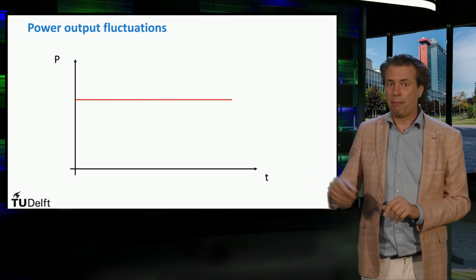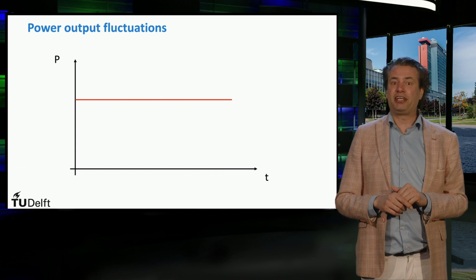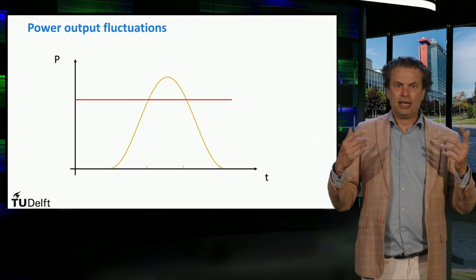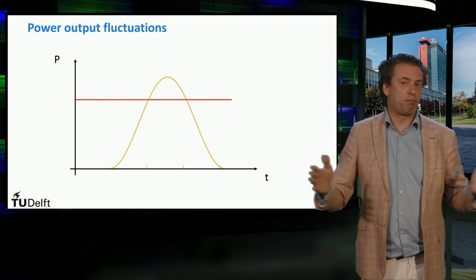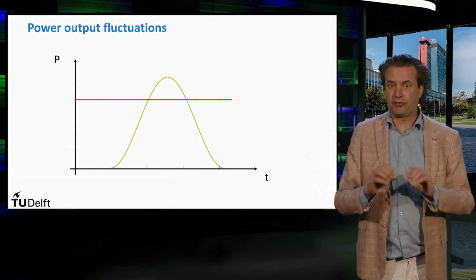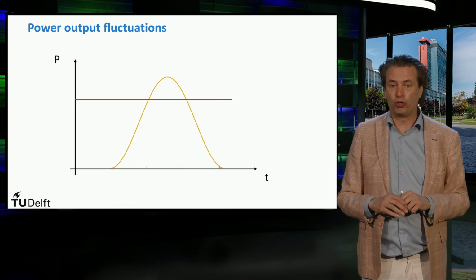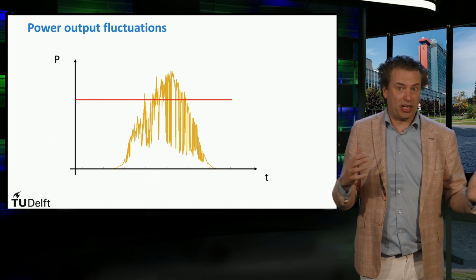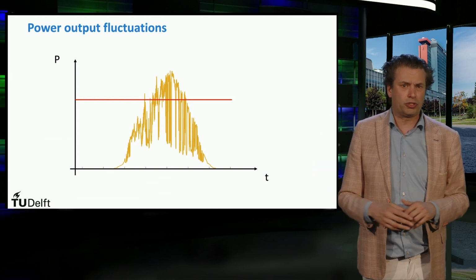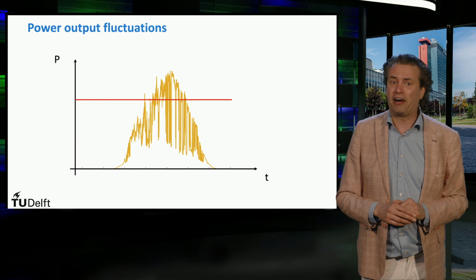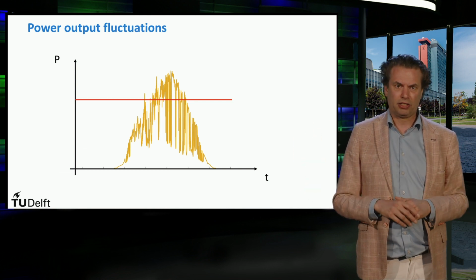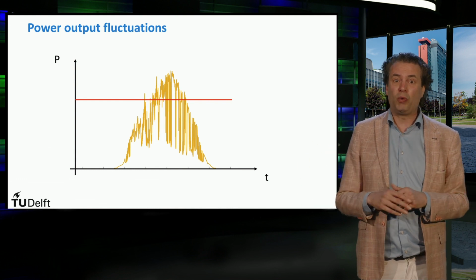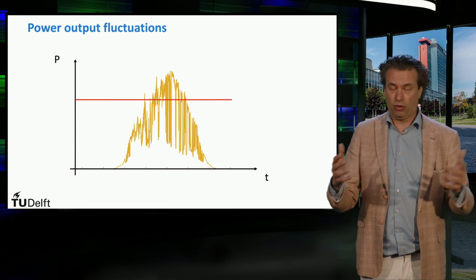In fact, PV systems show a peak when the irradiance is at its maximum over the panels. This usually occurs in the central part of the day, while during the night the electricity provided is minimal and even close to zero. More in detail, due to the rapidly changing weather conditions, such as the presence of clouds, the output power is likely to vary on a second or minute basis. In this scenario, these short-term fluctuations can cause problems with the quality of the power that a load receives.